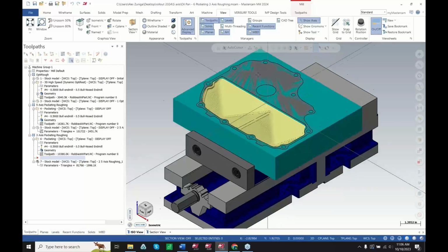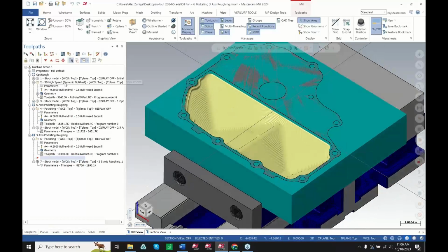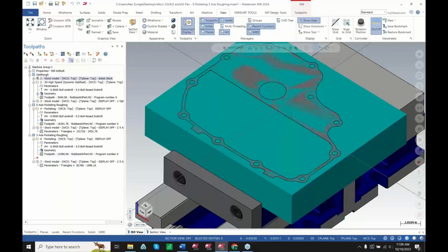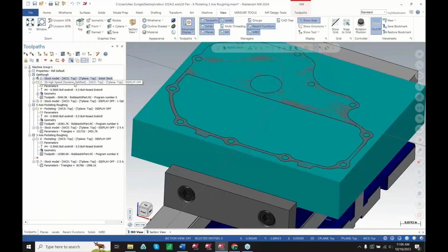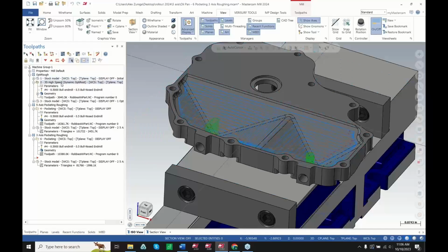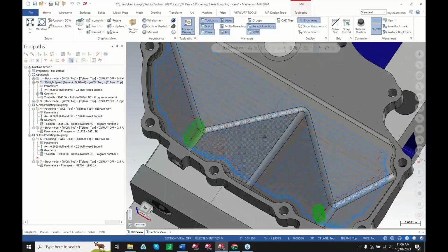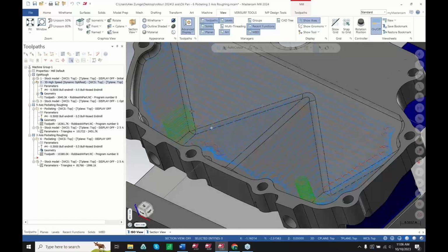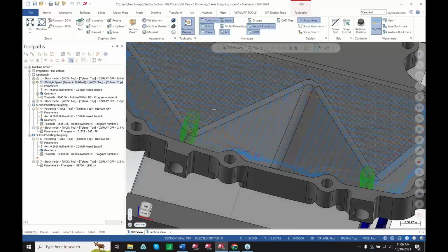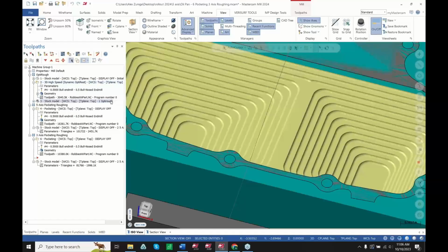The last enhancement for 5-axis is just another type of option that you could potentially use. So this is going to be kind of the best of both worlds when it comes to roughing. So typically when you rough out a pocket in 3-axis motion, you can use the good old-fashioned OptiRough here. Great toolpath. I love it. I use it as much as I can.